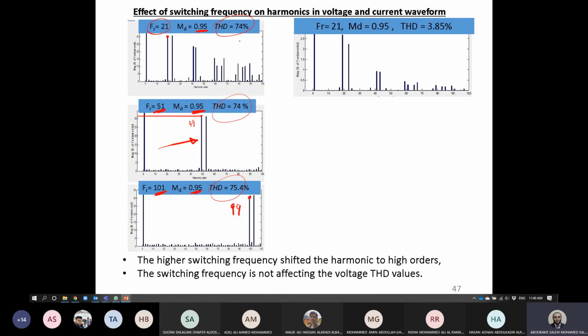Firstly, this was the performance at frequency ratio 21. For that waveform, you will have current with a higher value also here. And it seems here, Shabab, at that value, the impedance is not that high. The effect of frequency is not very high. Why? Maybe the inductance impedance itself is small, the reactive part is small. So as you can see, it's not 25, sorry, it's 2.5. So the 30 component became 2.5. This is at order number 19, like that. So the 19th order is appearing here, attenuated.